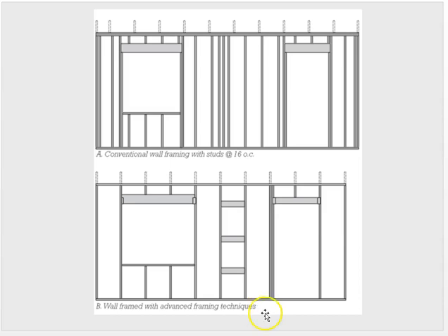Producing less wood waste. So again, we just reviewed what happened up here, and this is supposed to be the finished product for the advanced framing technique. So the differences are where we typically have double studs here, or a stud and a king post here holding up the header. We take that out and we just simply have some sort of a blocking or something, I'm not sure what the detail is, that reduces this double down to a single. So we see that at all these locations.